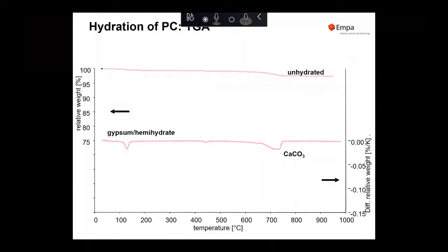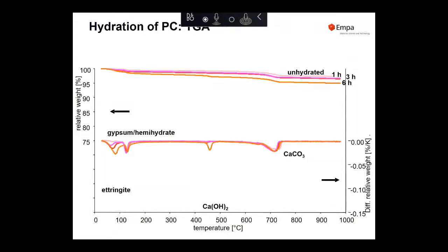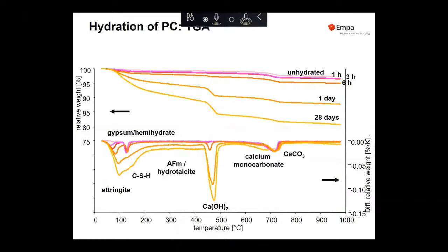Maybe just to get back to a bit more scientific level, if we look at the changes during the hydration of cements, we can follow it by a number of different methods, for instance, by TGA, thermogravimetric analysis. And one thing we start to see is that we bind more and more water, because basically with TGA, we measure the water loss of a solid phase by heating it, and the more loss we can observe during this heating, the more water we had initially present.